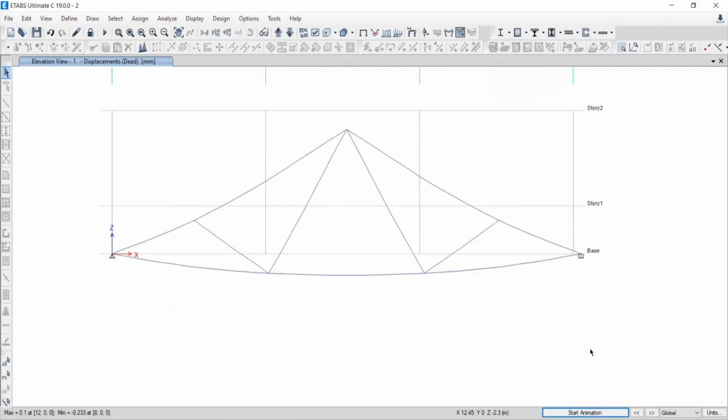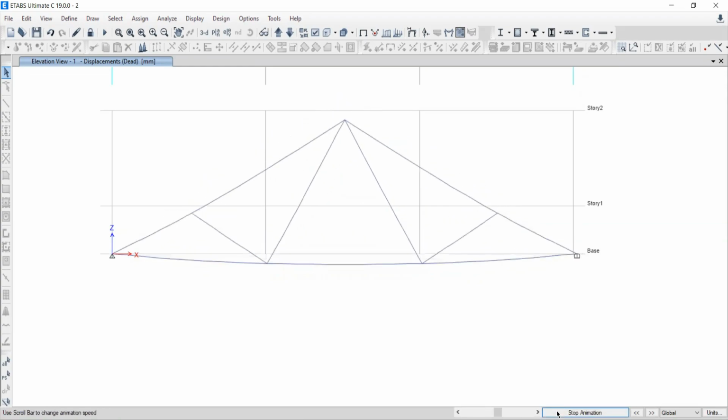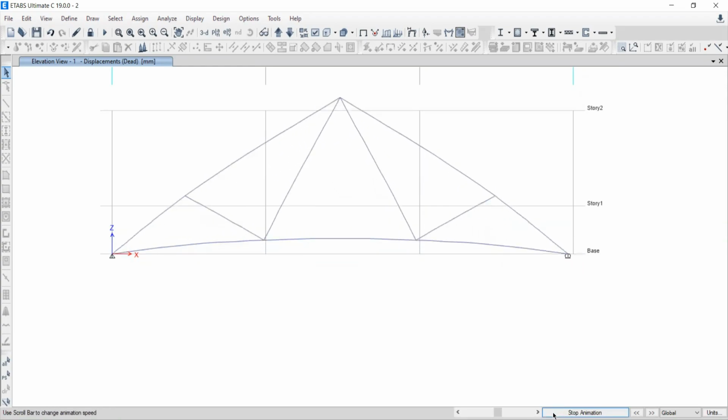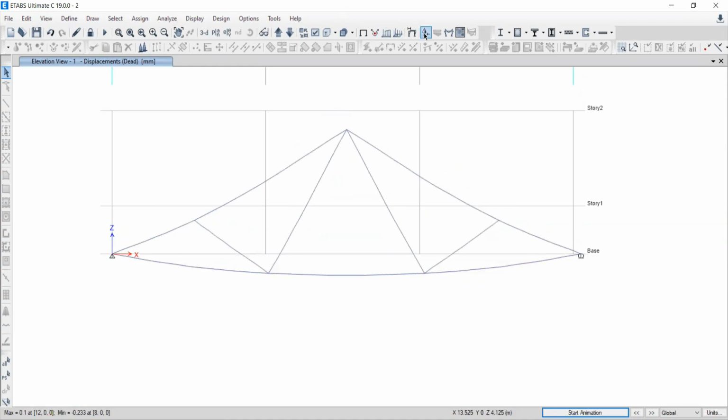For a long time we have been understanding that your fixed support cannot move anywhere. Your hinge support cannot move anywhere. Your roller support is moving along the translational direction only. So this is the proof. Your hinge support has restraint in translational direction, X and Y, and is free about rotation.